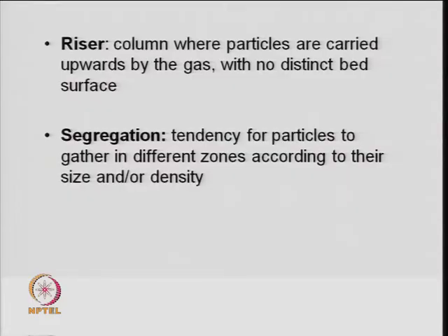So, in the riser you will have more and more catalytic cracking in FCC type units. Most of the cracking takes place in the riser part. Generally the diameter is small but the height is very large, of the order of 10 or 15 meters, and the velocity is high through it. So, coke formation is to be minimized, especially when you have a higher range of hydrocarbons.